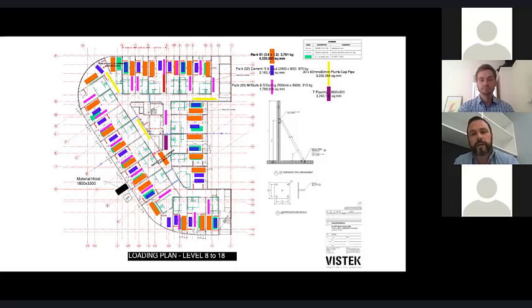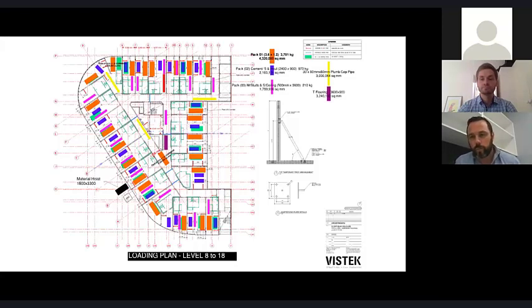And when you're comparing that to a timber structure and having to put load bearing elements in place of those internal apartment walls, the cost starts really escalating, because you're comparing a 10mm plasterboard wall, non-load bearing, to a load bearing, fire rated mass timber wall or even lightweight wall. Yeah, so with an additional acoustic wall. Yeah, totally. And this is where the hotels tend to be a lot more cost effective with these types of solutions. When you compare, not to say apartments can't be, but just when you compare them, there's an advantage there when you look at these hotel rooms.